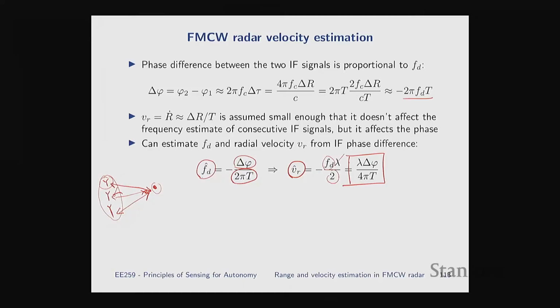If your target is too close, then yes, you can pick up different Dopplers on different antennas because of exactly what you brought up. But for us, we assume the target is far away, the range is almost the same with respect to all the antennas, and the antennas are really close to each other. But if the target is very close, can we estimate the tangential velocity?